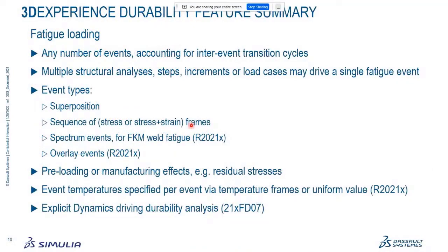Our loading covers pretty much all of what FE Safe can do at this point. Superposition, sequence of frames. For FKM, there's a spectrum. Overlay events are like in FE Safe high frequency events, where you can overlay one event on top of another, or multiple events can be overlaid on a sort of a base event.